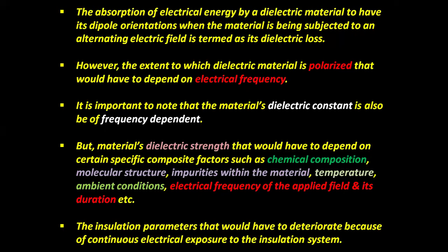But a material's dielectric strength depends on certain specific composite factors such as chemical composition, molecular structure, impurities within the dielectric material, temperature, ambient conditions, electrical frequency of the applied field and its duration, etc. The insulation parameters deteriorate because of continuous electrical exposure to the insulation system.